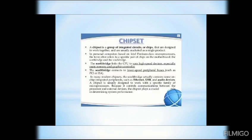Chipset. A chipset is a group of integrated circuits or chips that are designed to work together and are usually marketed as a single product. In a personal computer based on the Intel Pentium class microprocessor, the term often referred to the specific pair of chips on the motherboard, the north bridge and the south bridge. The north bridge links the CPU to very high speed devices, especially main memory and a graphics controller. The south bridge connects to the lower speed peripheral buses such as PCI or ISA.